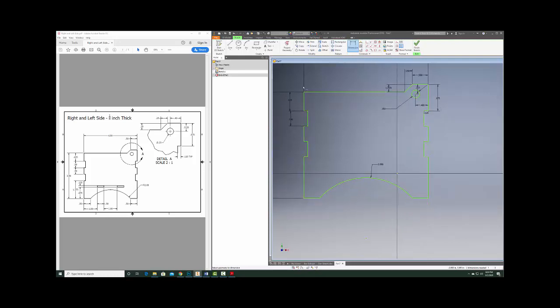Lastly, I think I need to put in those square rectangles, like you said. So I just use the rectangle tool here. I'll show you guys. So rectangle, really easy to use. Put one there, put one there. Okay, dimension 0.5. Yep. I could have set those equal to each other and not had to dimension. I am going to use the collinear just to double check so that I know they're even with each other. It already had that set up, so we're good.